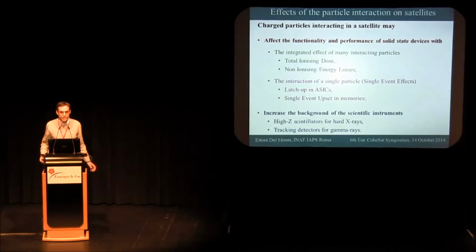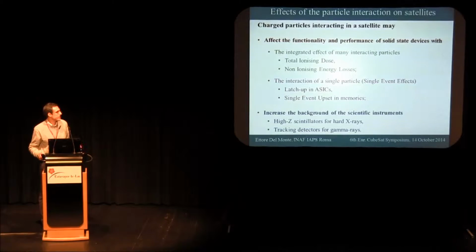Basically, when they interact in satellite instrumentation, they can affect the functionality and the performance, for example, of solid-state devices, and we may have, broadly speaking, two types of effects. The first one is the integrated effect of many interactions, and this is generally under the name of total ionizing dose or non-ionizing energy losses.